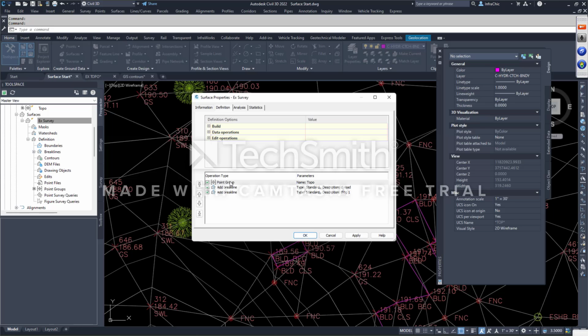What's on top is built first. What's on bottom is built last. These arrows on the left help you move them. So I can take that very last break line we did, and I can use an up arrow at 1, or I can down arrow at 1. When I do that, the chevron shows up. This is the rebuild-me, something-has-changed chevron.